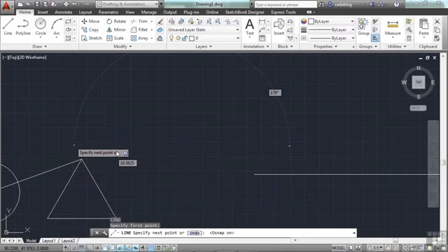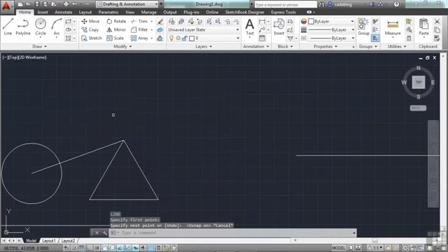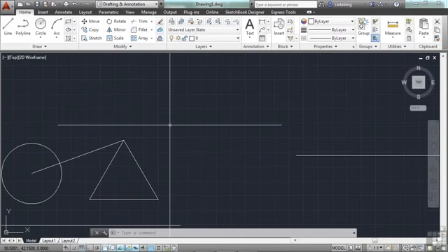Now it will take the line and follow it and project it, whichever line it is I'm drawing from. And so I can go or snap to places that don't exist but are sort of inferred or arbitrary. So that's a very useful tool as well. Again, these tracking devices, the polar tracking and the O-snap tracking, we'll talk about them later on in more depth in a section. But the function keys turn on and off these certain tools that allow you to draw more accurately, or draw better even. Make sure to watch the video pertaining to each of these tools for more in-depth descriptions for them.